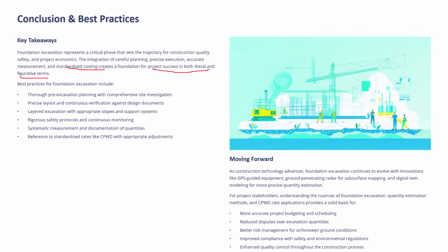figurative terms. Best practices for foundation excavation include thorough pre-excavation planning and comprehensive site investigation, precise layout and continuous verification against design documents, layered excavation with appropriate slopes and support systems, rigorous safety protocols and continuous monitoring, systematic measurements and documentation of quantities, reference to standardized rates like CPWD, and appropriate adjustment.